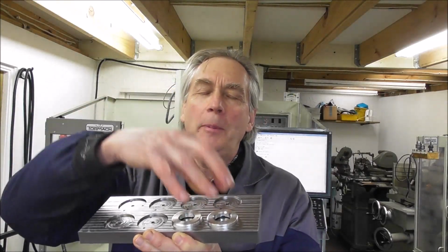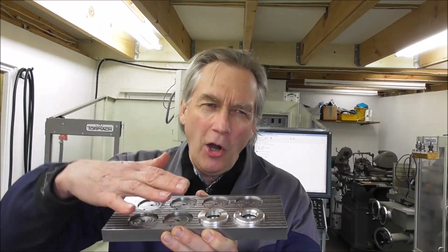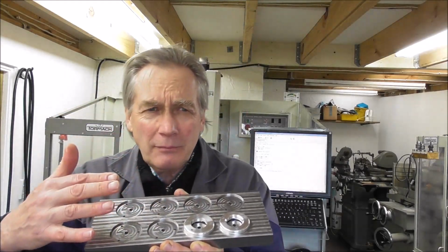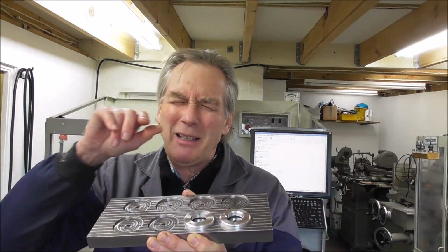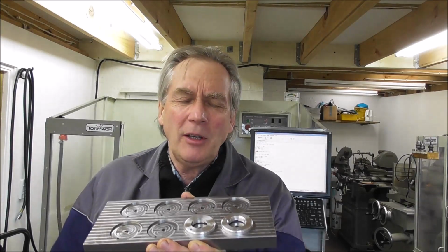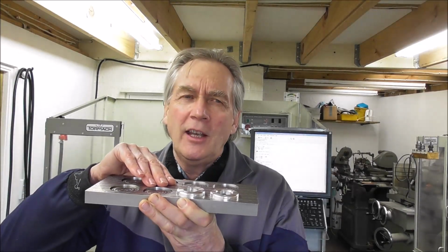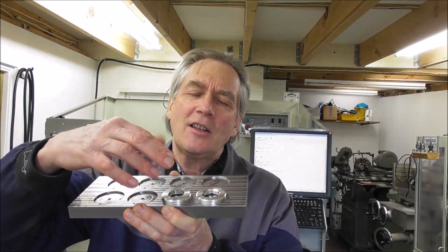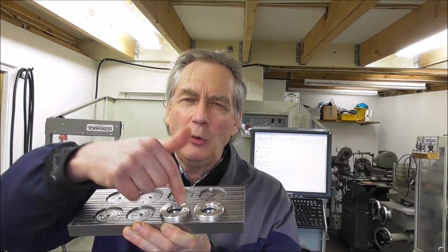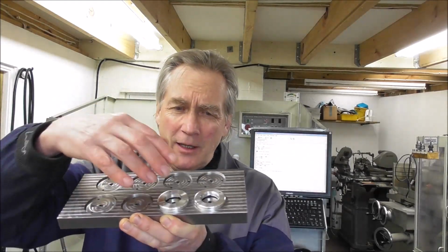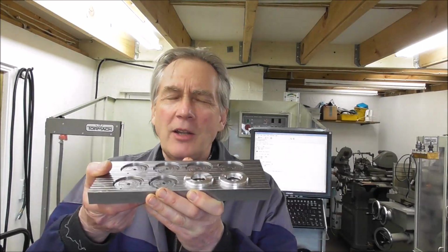So instead of just copying and pasting the code 8 times and then putting a G54, G55, G56 at the beginning of each one and so on, which is a bit rough and ready, I'm going to use a more elegant process using subroutines, so I just have one bit of code and a little bit of subroutine instructions so that it goes back through and loops the code 8 times to machine the different parts. So I'll go through how you might do that now.